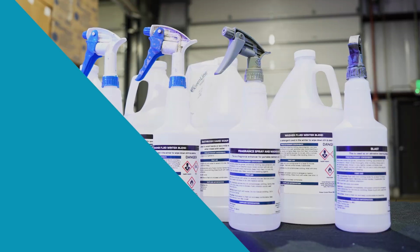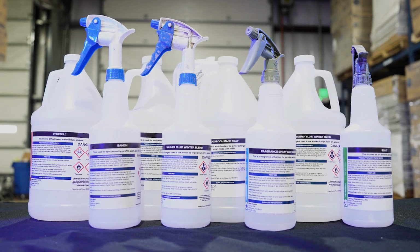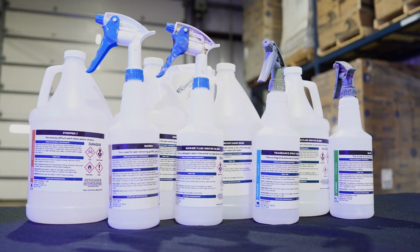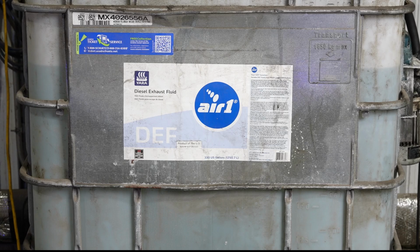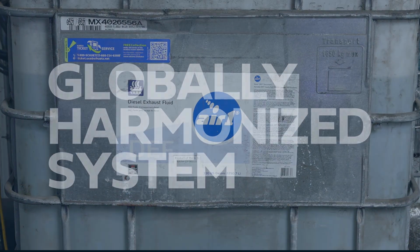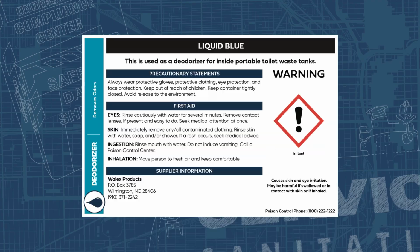The core of Hazcom is making sure chemical users have the information they need right when and where they need it. This is done through container labeling. Hazcom uses two types of labels, shipping labels and workplace labels. Containers leaving a manufacturing facility must have labels that meet the globally harmonized system, also known as GHS standards.